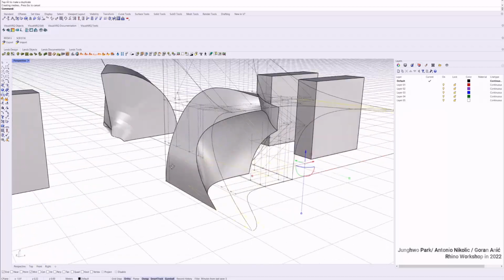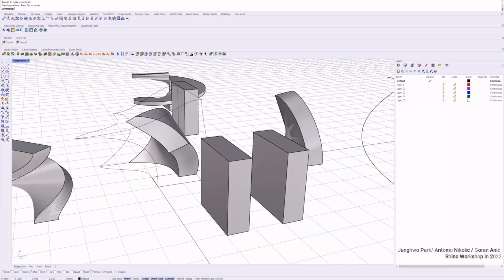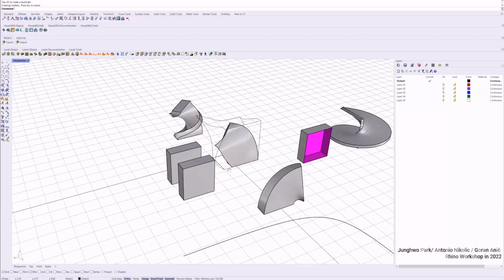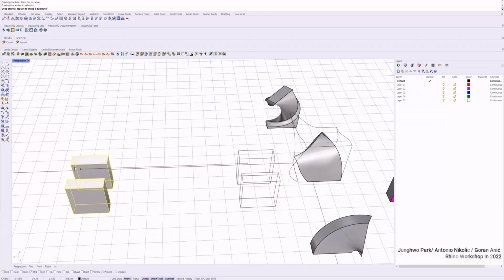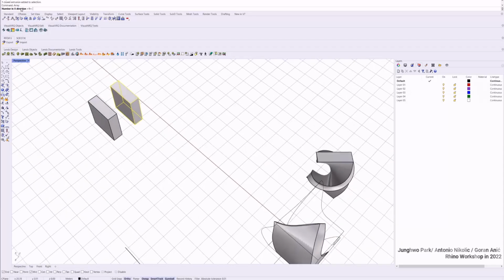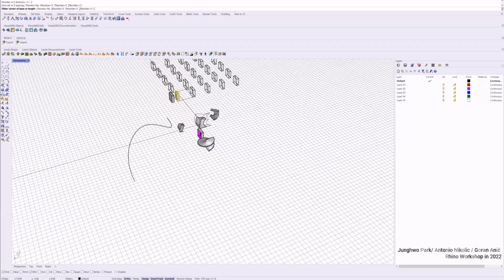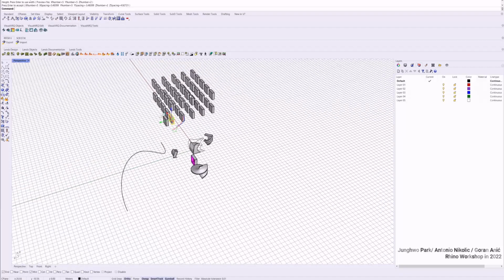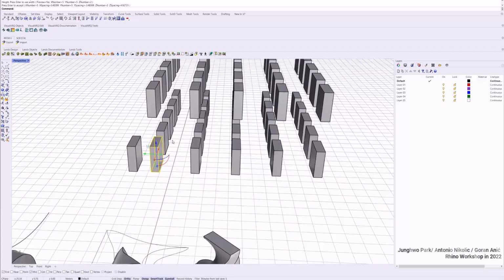This is also very nice. Yeah? And I think you can also do multiple objects. So what I'll do, I'll array this box 5, 5, Z 2, spacing from here to here. I think, yeah. So we array this object.